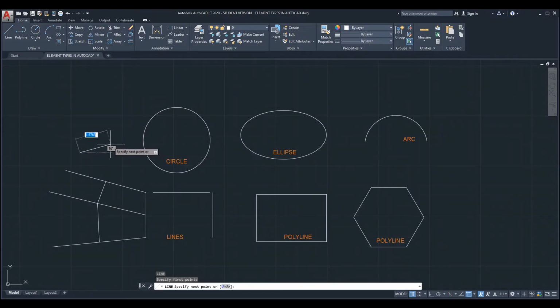I'm gonna zoom in and out to hide it. So right now we can't see the center of the circle. For us to be able to see it, you just need to touch the perimeter of the circle with the cursor, and then here we will get a small plus sign in the center of the circle, and if we move the cursor toward that, you will see it says center, and that will give us the center of the circle.